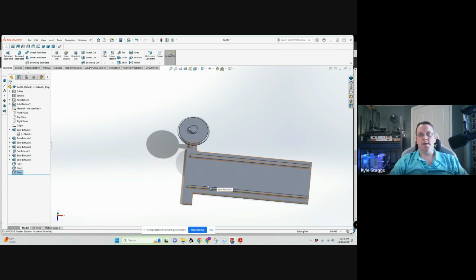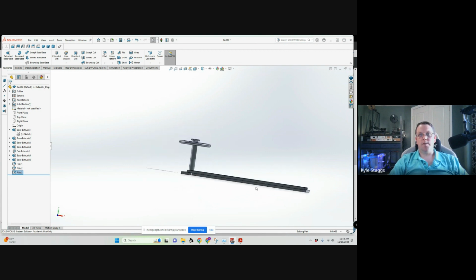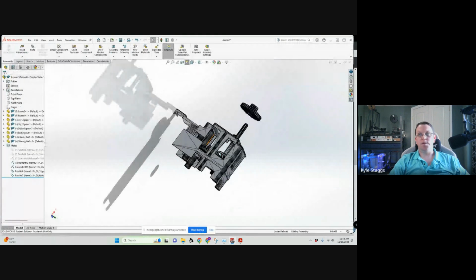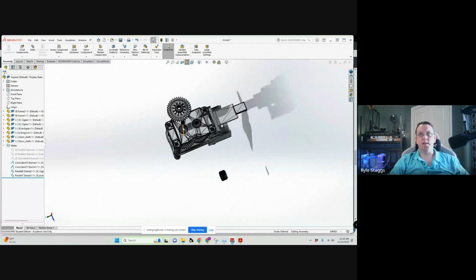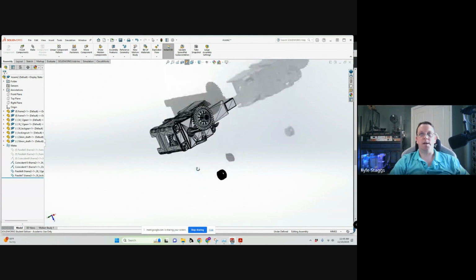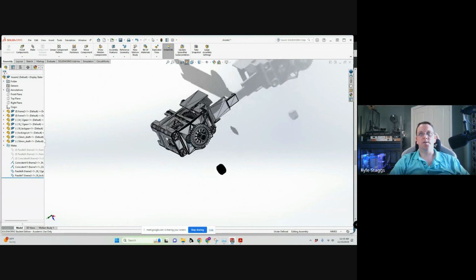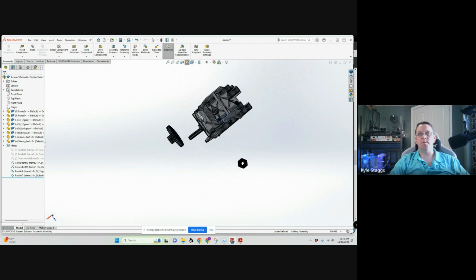You're going to want to carefully space out your axles from each other and spend a lot of time really building out at least part of that assembly, so that you can get a good sense of how far apart these have to be. That way, when I print them, they're going to be pretty close to exact, and I'm not going to have issues where I misaligned the holes and they're too far apart, the gears don't engage, and they strip out, or too little, things like that.